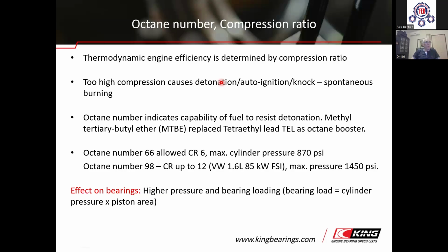It is worth increasing the compression ratio as much as possible in order to increase the efficiency of the engine. However, too high a compression ratio causes engine detonation or knocking, when the charge burns in an uncontrolled explosive spontaneous mode instead of progressive flame propagation.